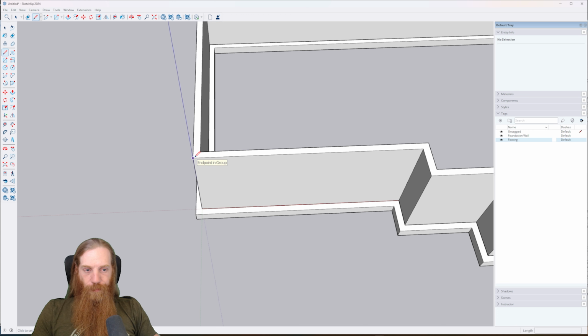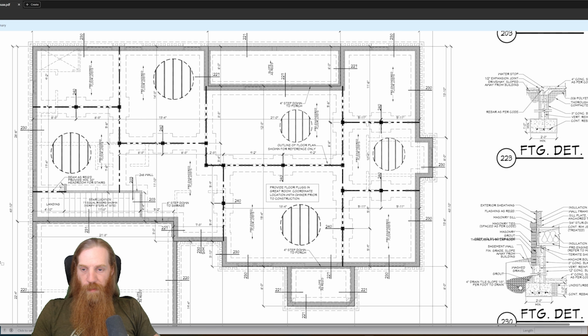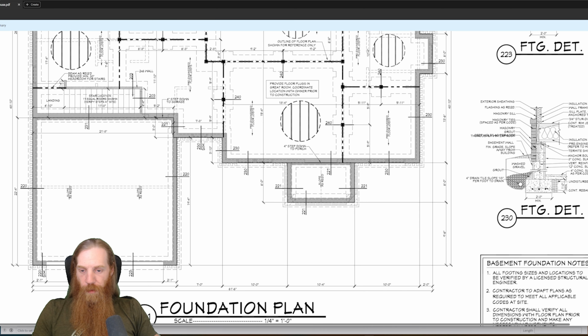Let's just do the garage the way that it shows on the plans with the width that it shows, which is 22 foot 2 from exterior to exterior. Although I don't think that's actually going to be right. Probably not. So, yeah, let's go ahead and do that width. So we had 21 foot 6 for the interior width. The garage is only going to have a 6-inch wall. It's not going to be an 8-inch thick wall like we did for the basement foundation. The garage foundation is basically a stem wall. 6-inch thick foundation should work fine.